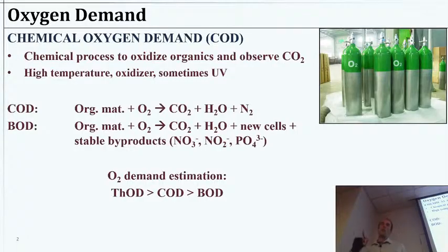We generally don't use it for the wastewater field because we will continuously do these BOD tests, and that's a better estimation of the biological stuff that we really are concerning ourselves about. But I wanted to mention it. It's essentially taking some strong oxidizing conditions, maybe it's hydrogen peroxide and UV, maybe it's temperature and perchlorate, something highly oxidizing, and blasting it. And it's going to convert things like the organic matter, maybe some things like ammonia. You're adding enough oxygen, and you're taking that stuff to CO2, in this case, for the ammonia case, to nitrogen, things like that.